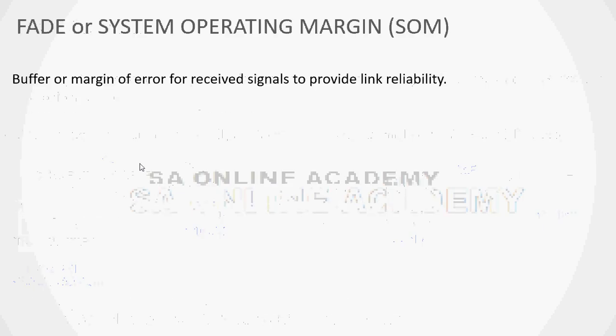So fade margin is a buffer or margin of error for the received signal to provide link reliability. While designing a solution, if you have a receiver sensitivity of minus 60, minus 50, minus 40, minus 30, keep some margin. Instead of minus 30, you would mention that my receiver sensitivity is minus 50 or minus 55, at a lower level, because while transmitting there are a lot of fluctuations or changes in weather, and because of these changes in the medium, your signal will fluctuate.